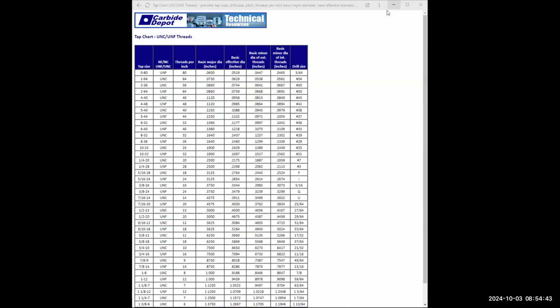All right, now I want to work with this hole here. Now this is a little tricky. This is a counterbore hole, and it tells me the depth. Pay attention now, very clear. Make sure you're paying attention here. The depth of this counterbore is 1 inch. Now, watch. I'm going to draw a construction line right here. Just a simple construction line. And I'm going to offset that 1/2 inch, 0.5, enter.